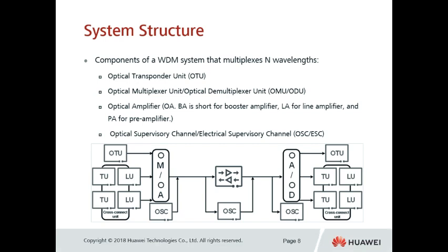The optical demultiplexer can drop all the services from the main path at the same time. But this unit has one disadvantage: the insertion loss is very high. The attenuation is very high. If our service has already transmitted a very long distance, the power is already too low. If I don't amplify it and connect it with the OD directly, the signal will decrease a lot.